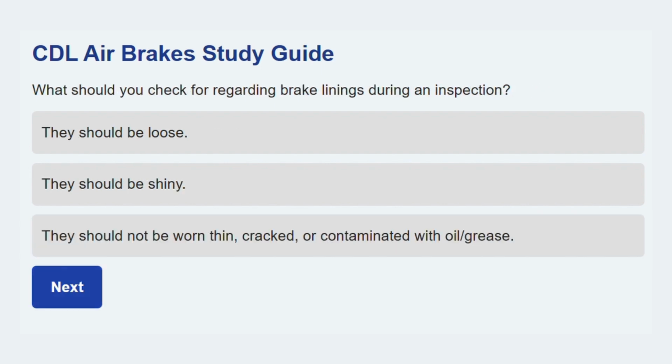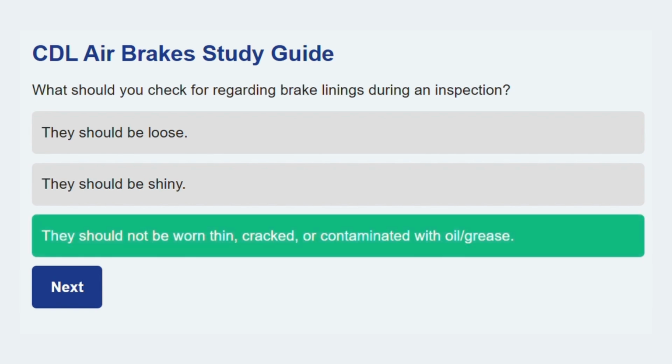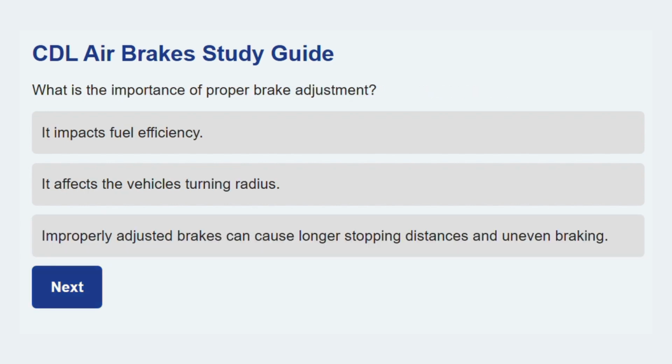And the next point. What should you check for regarding brake linings during an inspection? They should not be worn thin, cracked, or contaminated with oil or grease. Worn or contaminated linings reduce braking effectiveness and can lead to brake fade.